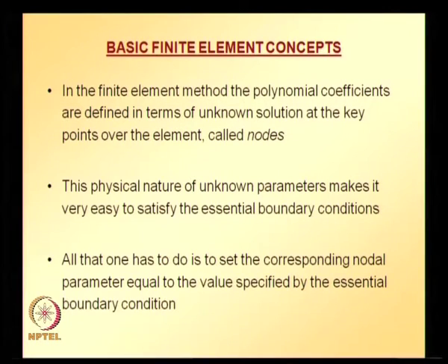And why is it so simple if we express polynomial coefficients in terms of nodal values? All that one has to do is to set the corresponding nodal parameter equal to the value specified by the essential boundary condition. So this is why it is fairly easy to apply essential boundary conditions in finite element method.